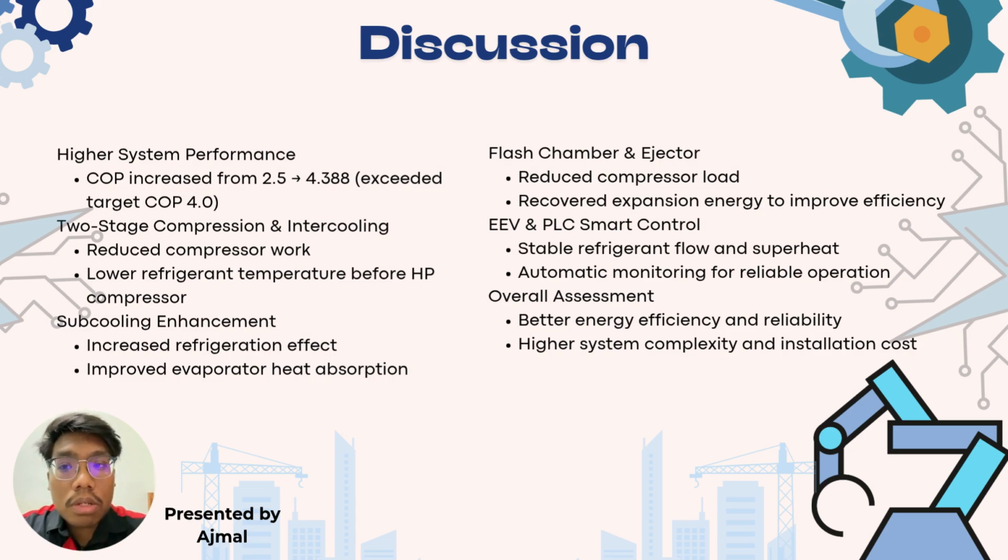So this helps reduce the compressor load and increase the overall thermodynamic efficiency. Lastly, the electronic expansion valve, or EEV, and the PLC-based smart control system. So this provides automatic control of refrigerant flow, pressure, and temperature. So this ensures stable operation under different cooling loads and improves the system reliability.